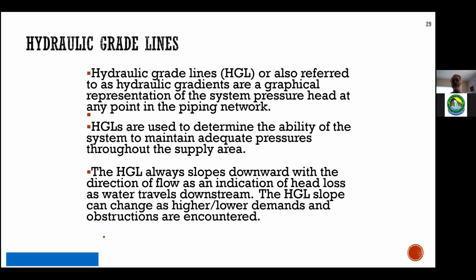And every 100 meters out of that kilometer, you tap the water main and put a pressure gauge on it, and at the same time put a clear plastic tube. You could mark where the water stops, because the water is going to stop eventually at the top of the energy, right? As soon as it loses energy, you could draw a mark on that tube and then connect them all up, and that is a hydraulic grade line.